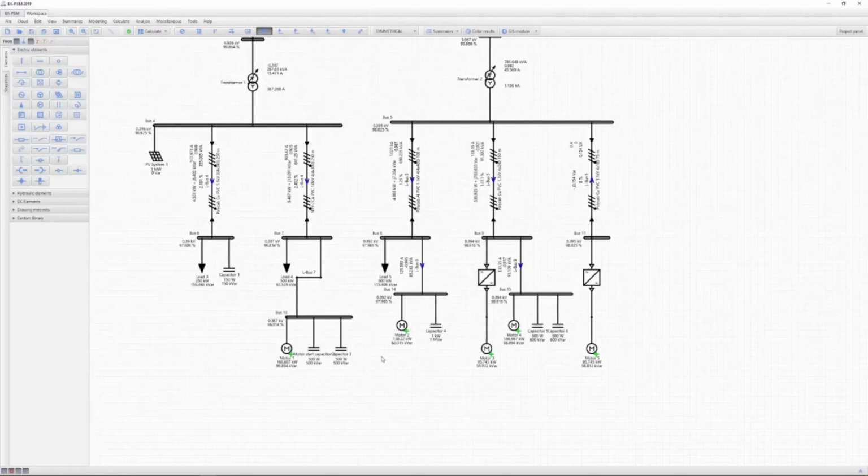But now, given all the calculations we see here, we have to export it to the project panel. And I'm going to show you how to do it now. When you're done carrying out calculations on your given scheme and you don't want to do the calculations 2 times, in the upper toolbar you can see there are a lot of pictures. The first one is display power flow results. That is, if you have carried out power flow results previously, you can press and check the results that was before. If you want to go back to motor start results, you just press motor start.